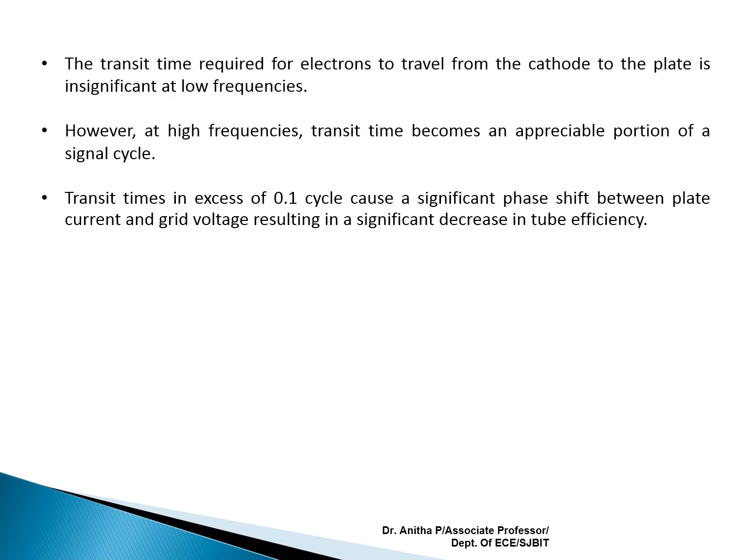But if you operate the same circuit at very high frequencies, the transit time becomes an appreciable portion of a single signal cycle. Because at high frequencies, the f value increases, and the wavelength, which is inversely proportional to frequency, obviously reduces.